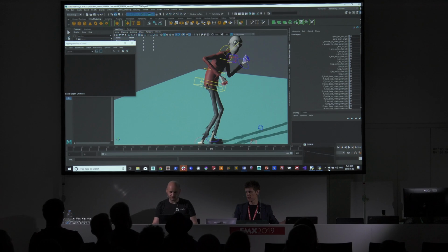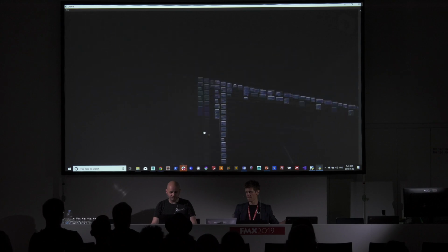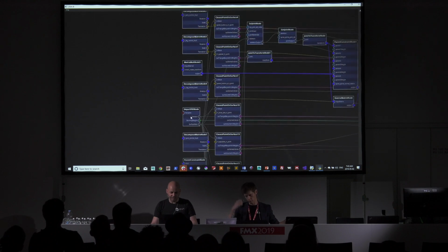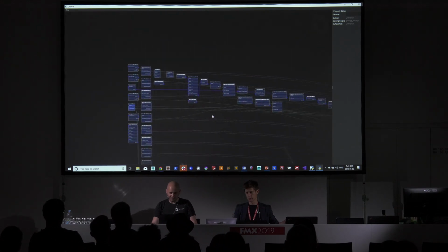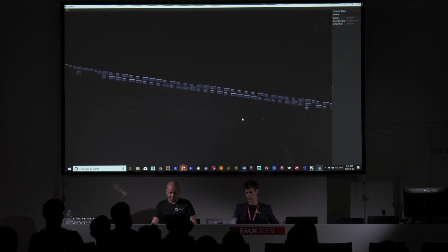And I'll give you a sneak peek at the authoring experience. This is all early days from the UI standpoint, but it will evolve really quickly now that the underlying API has come quite a ways. This shows you the nodes that might exist in your standalone thing. In this case, we're importing an FBX, and that has our skinning weights and our joint hierarchies and our meshes. Then we build our IK and our FK, apply the skin cluster, and do all that sort of stuff. And this graph is then executed live inside of that ZOA player inside of Maya. Or eventually, you'll be able to run it standalone as well.